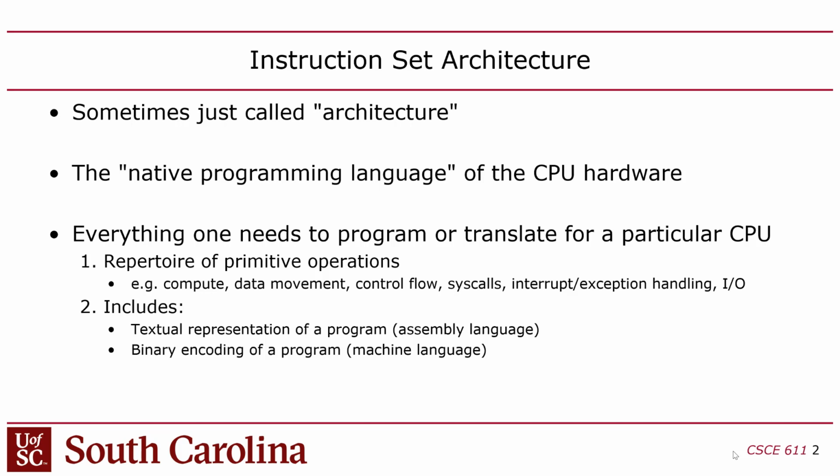And so as I mentioned, there's an assembly language. This is what you actually would type out. It's a human readable text representation. And then there's a binary encoding of that, where an assembler translates each one of those instructions to a binary representation that's actually run on the CPU. You guys have to understand both because you're going to be writing SystemVerilog that's going to be interpreting the binary representation of these instructions and then implementing them using data flow paths, register transfer paths. So it's important that you understand not only the assembly language, but the machine language.